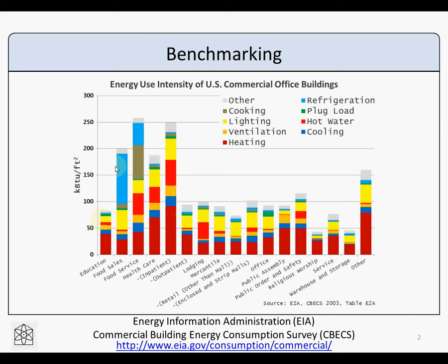And one unit of that is kBtu per square foot. If it's SI units, that's kilowatt hours per meter squared. And so we're expecting an EUI generally around 90 to 100 for these buildings. So you can take your energy simulation and see, does it match that? Is it much higher or much lower than that?